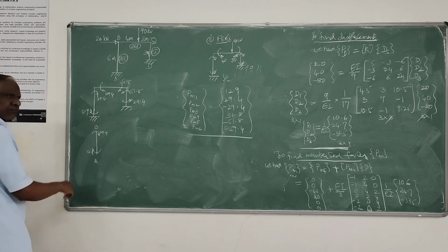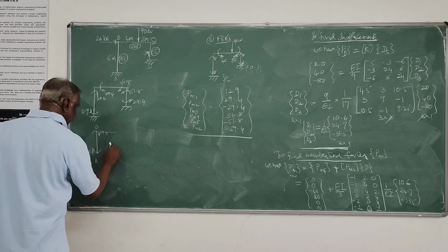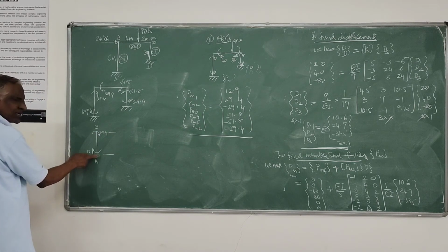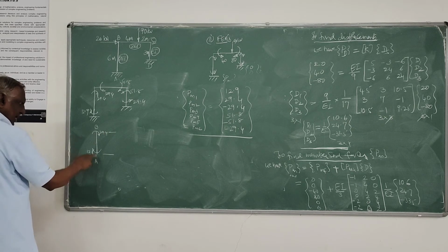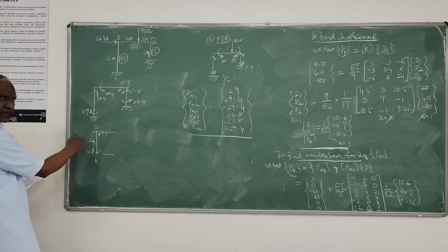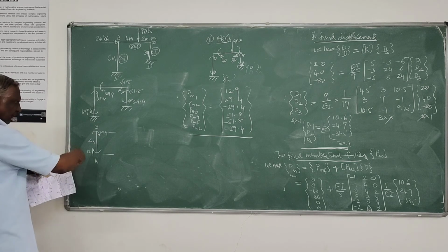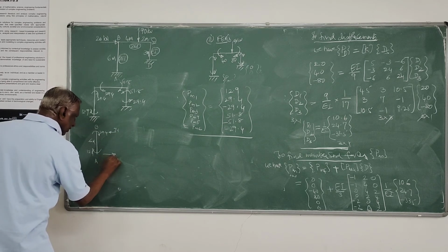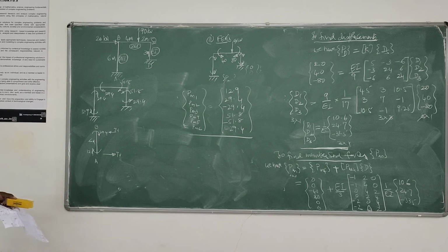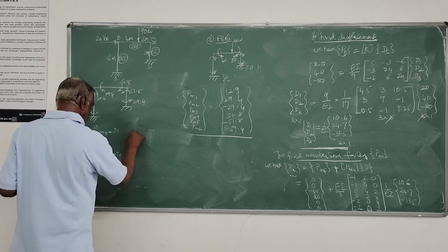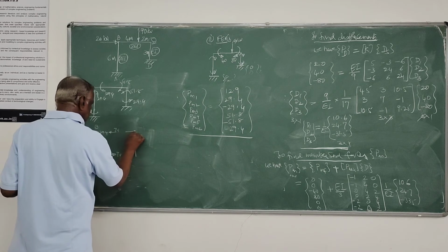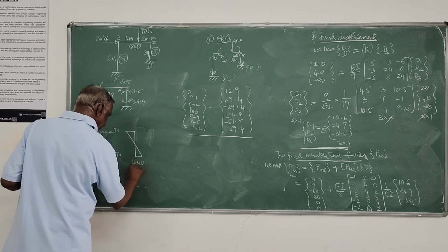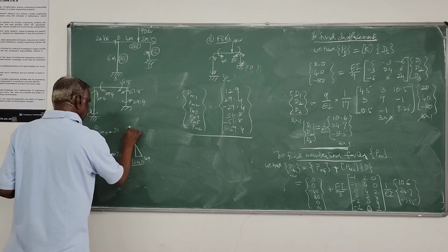There is no member loading, right? Hence only the shear force corresponding to this we have to compute. You take moment about this point, so this shear into this height of 6 meters, right? Then you can take the algebraic sum of the moments. So that value also, I think 7.1 you are going to get here. Here it should be equal and opposite because sigma V has to be 0. So therefore we can plot the bending moment diagram. So this is 29.4, 12.9, just like that. So this is your B and D, 12.9 and 29.4.